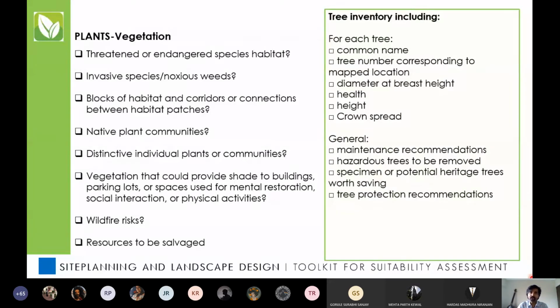So how do roots work? Roots basically go and multiply in those areas where you get more water. So when there is no water availability in the rest of that zone, because you paved everything, you've sealed the top, but you've only left an opening right next to the tree. What happens is most of the roots start concentrating in that particular area because it has to absorb maximum water for the tree to grow.